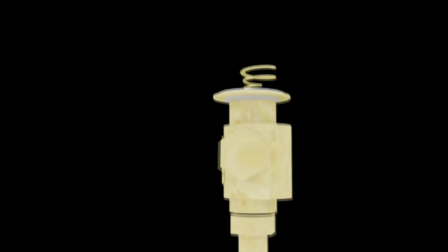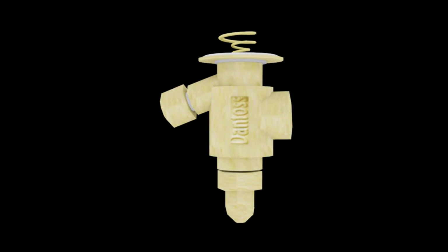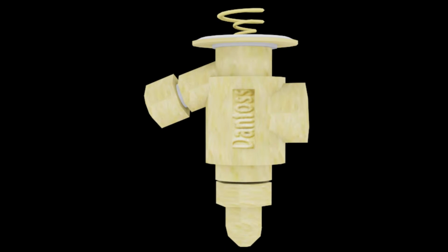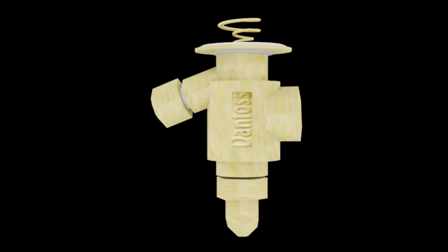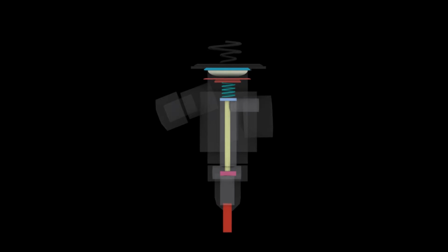Thermostatic expansion valve or TEV works based on the expansion of the mercury inside the sensing bulb fixed in close contact with the suction refrigerant line at the outlet from the evaporator and is responsive to change in refrigerant vapor temperature at this point. When the temperature in the refrigerator rises, the mercury inside the sensing bulb will expand. The expansion of this fluid will push the diaphragm downward together with the push pin when overcoming the spring pressure set by the manufacturer. This will lead to the opening of the valve and allows the refrigerant to flow through.